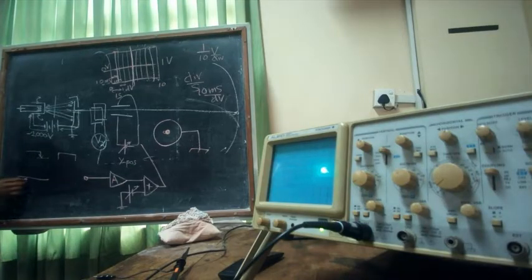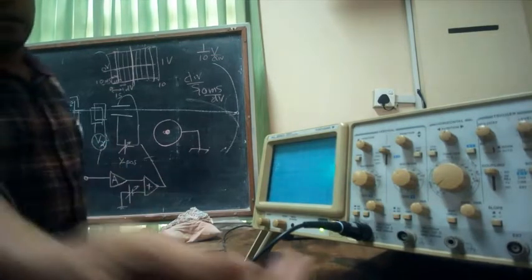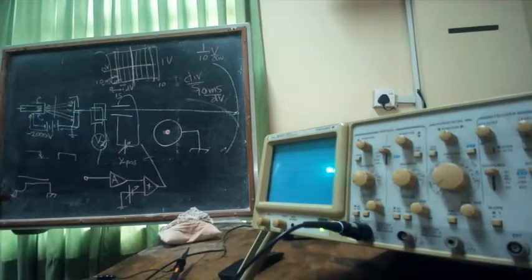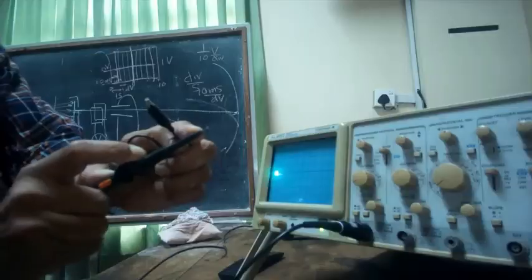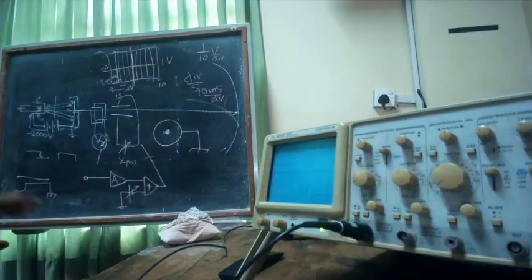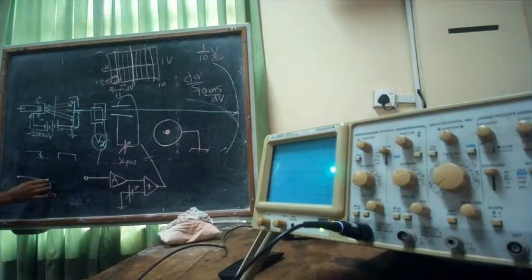That means you have the signal, the probe, and the crocodile clip. The crocodile clip that you have is connected to that chassis internally. That's the chassis. This is the probe wire, and this is the tip. It's connected here. Now, if it is DC connected, this directly connects to that.